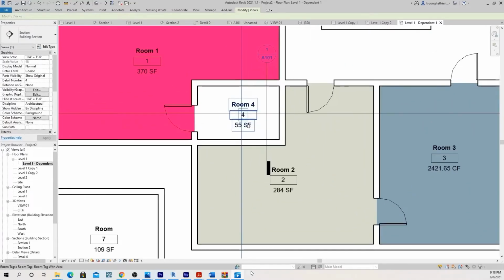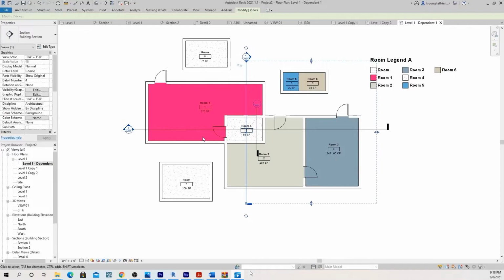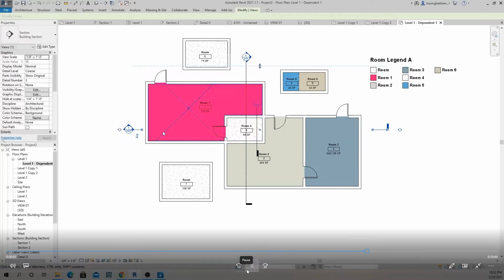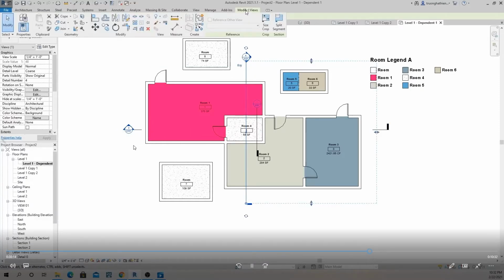Okay, I just move to how to create the section with the zigzag. In case you have a little bit of a problem, make it cleaner by moving the section line outside the object. You don't need to cross the object. You can do it like that.